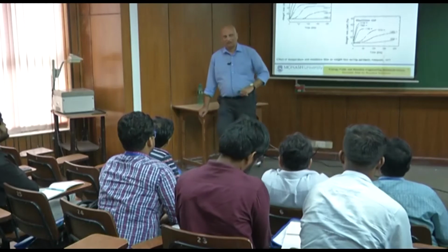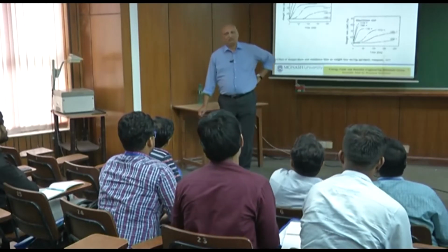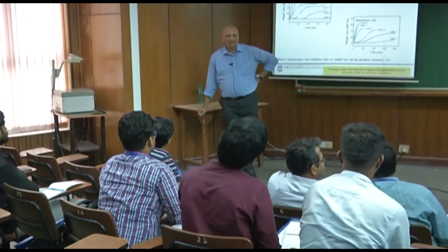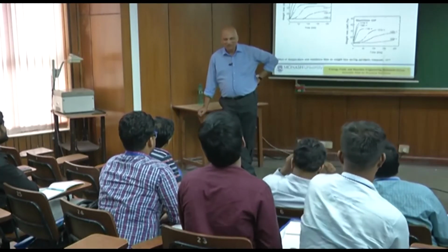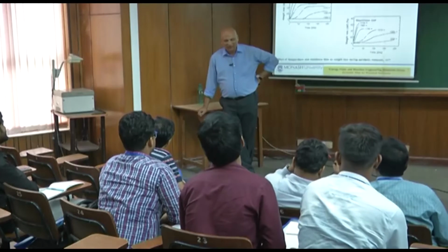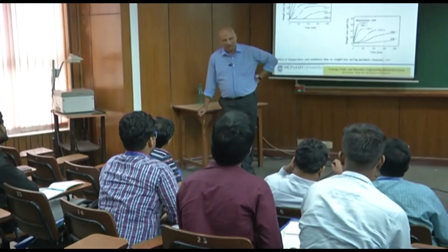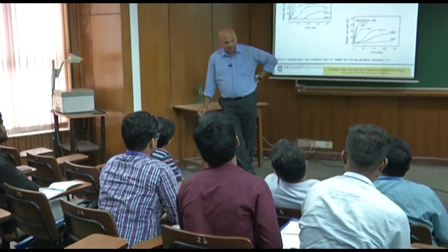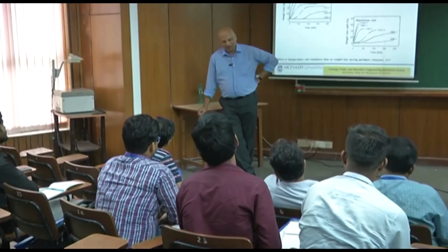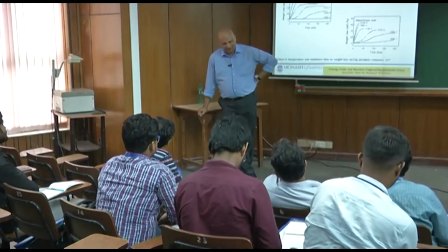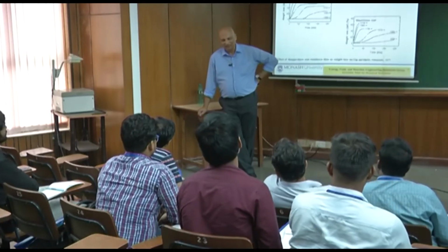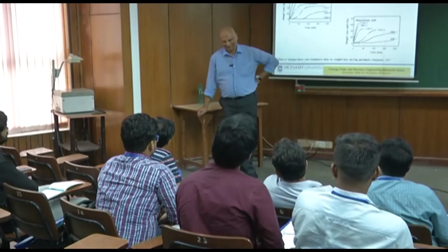But for the engineers to design, they need to know a certain number, based on which they will say, okay, if you tell me how much volatile is present at 900 degrees for 7 minutes, then I can tell you, from our experience, in-house data, etc., how much volatiles will be released at 1500 degrees centigrade for 7 seconds.